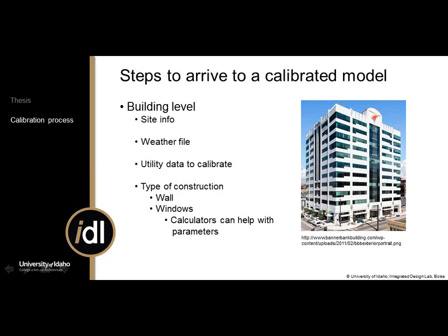Another thing is to simplify as much stuff as you can, because it will reduce simulation time and resources spent. For example, the Banner Bank has spandrel in the middle of the facades, and some details of walls that are different than other sections of the exterior facade.